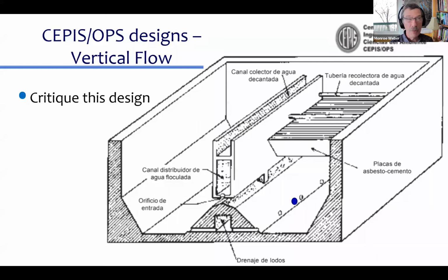I think this design was made before, well, I was just looking at their manual this morning, and they have a picture of plastic plate settlers that failed because they got brittle, which goes to another insight that Agua Clara has had, and that is that all water treatment plants should be under roof to protect the system from sunshine. This is a revolutionary idea in the world of water treatment, that you should have a roof over a water treatment plant. And that actually makes it so that plastic plate settlers work and are a solid option.